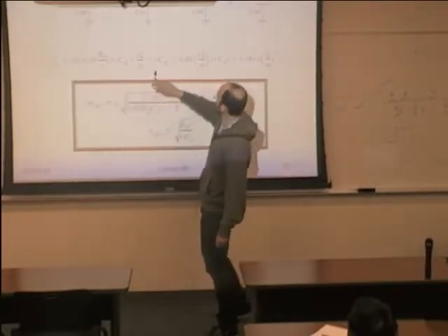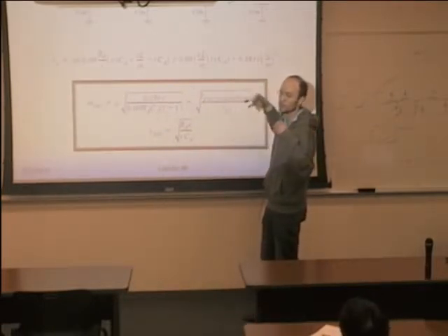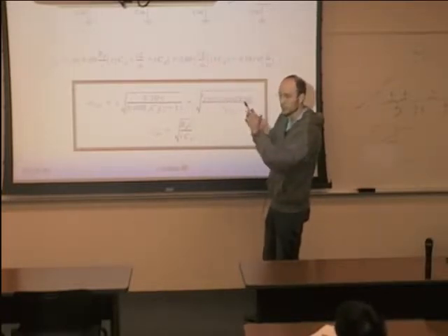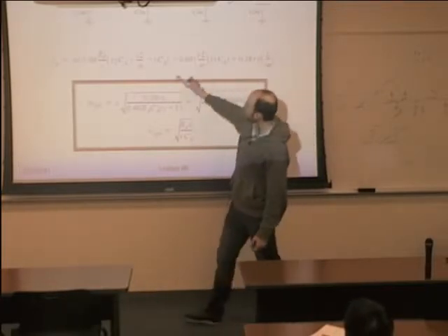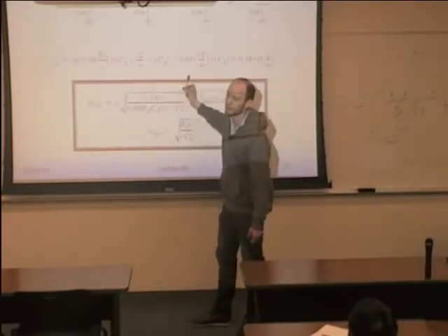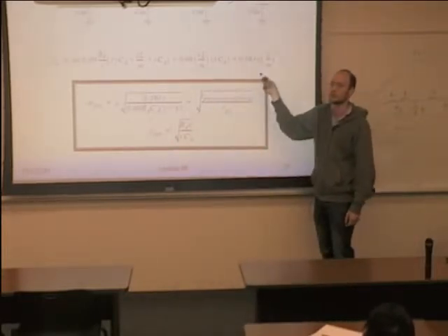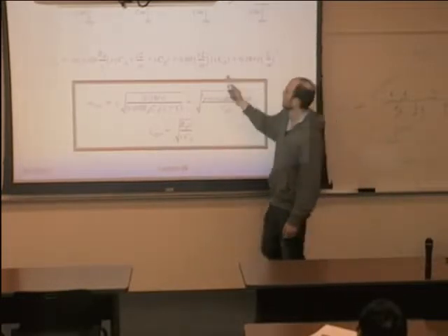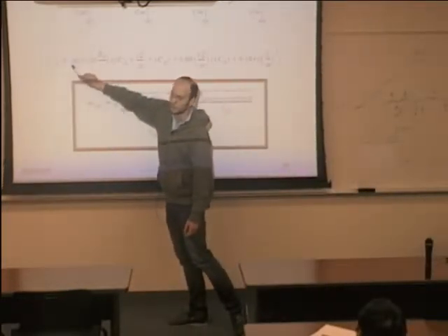So now look at what happens as you increase M, as you increase the number of buffers. Essentially, you make each individual line shorter, and therefore you make this thing between the parentheses smaller, because inside the parentheses everything decreases as you increase m. But you increase this multiplying factor.